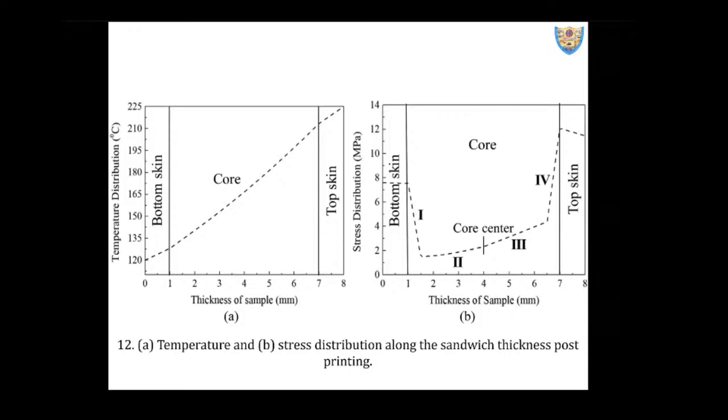Okay, because there are methods, very expensive methods, to experimentally measure the residual stresses. But in the absence of that, the simulation packages help us in knowing the range within which it is acting. And then we can do the annealing, we can put it one more time in the oven and try to reduce this, and we can definitely do that.